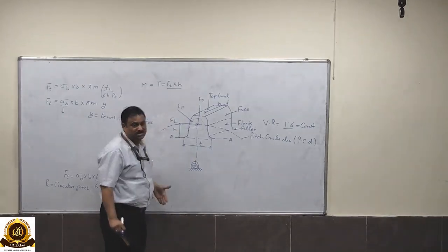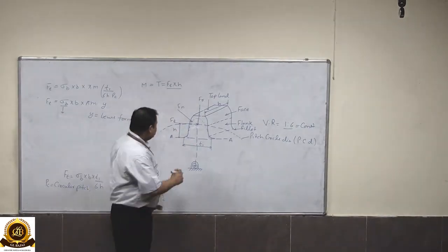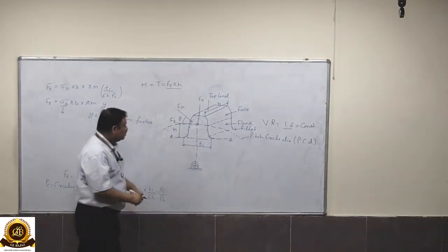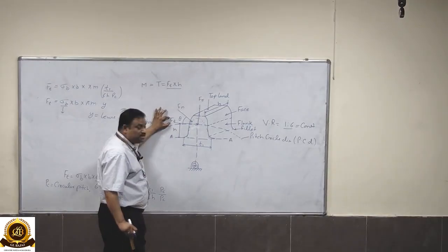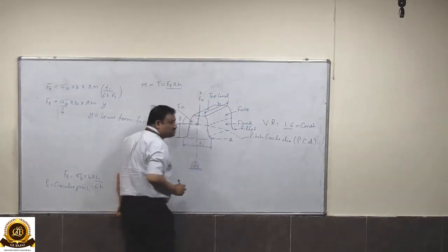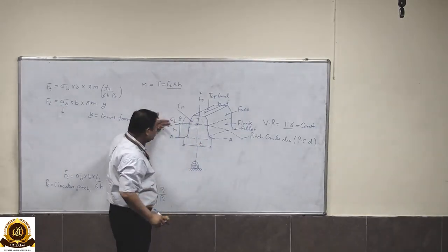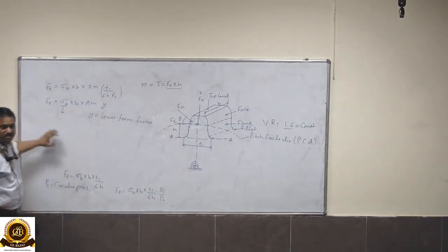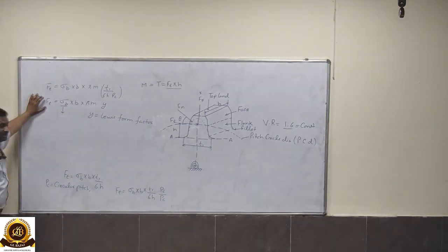These are also changing in magnitude. Now the angle between these two is, say, theta. So therefore this Ft is not constant. We are not taking this force into consideration, so we will consider only this force Ft, and the magnitude of this force is not constant. It means your gear is subjected to a fatigue load or fatigue stress.